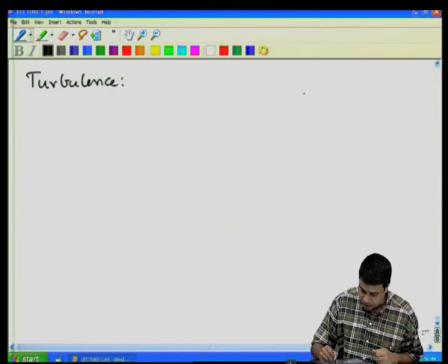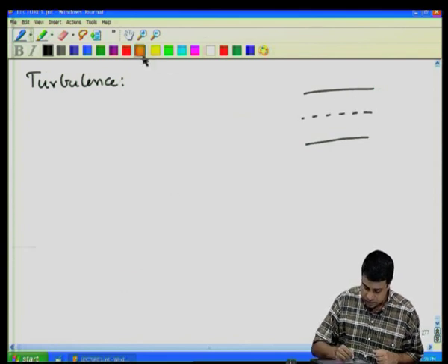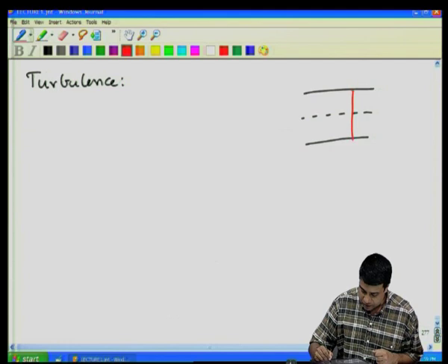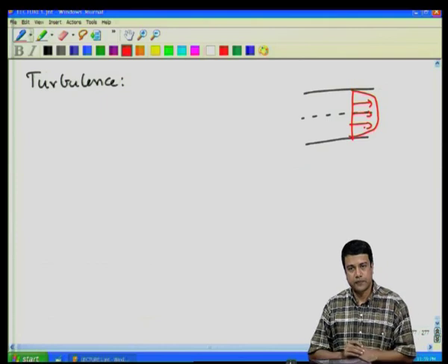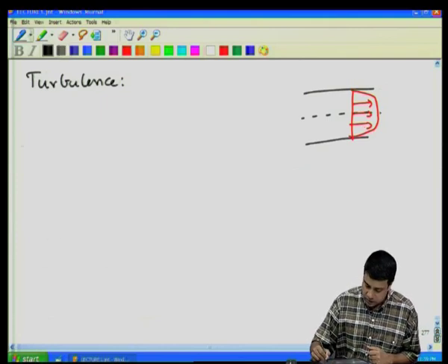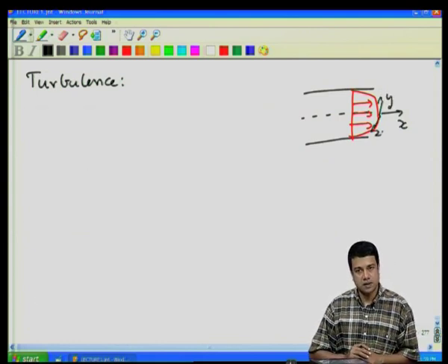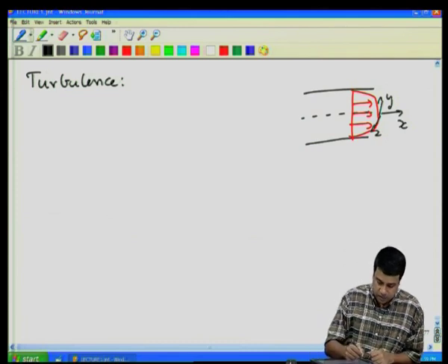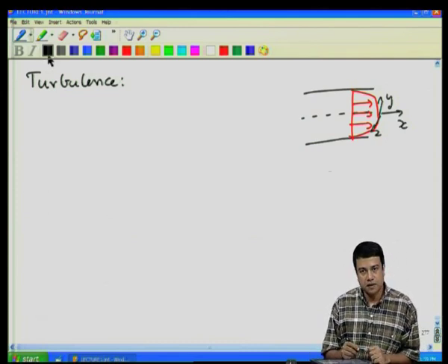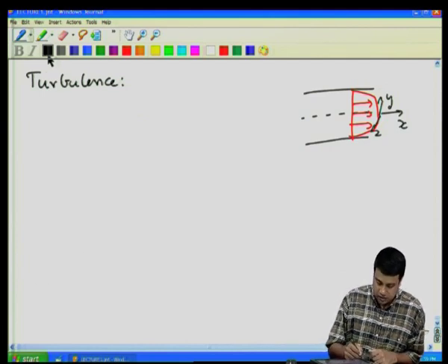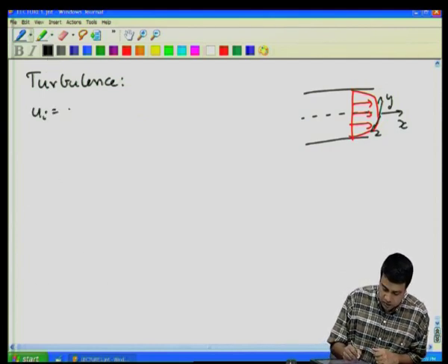our attempt at turbulence modeling. This is, let us say, a steady flow in a channel in which I have some mean velocity profile. And I will put a coordinate system there just for definiteness, x, y and z. So, the flow direction is in the x direction and y and z are perpendicular directions. I define the different components of the velocity u_i as the sum of a mean plus a fluctuation.